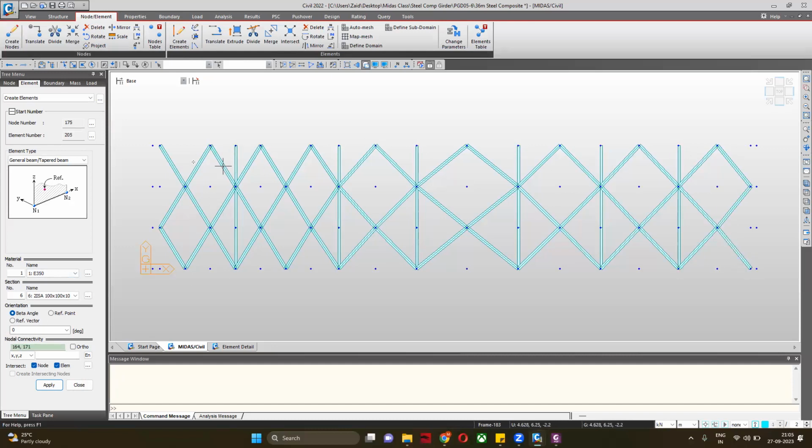It does not matter if our bracing is matching anything. This is just to resist when there will be sway, like the bridge will try to move in the transverse direction. So this bracing just provides the resistance, nothing else. It will take your whole bridge as one single part. Sir, the reason it is only provided at the bottom and not at the top is because the slab is there?